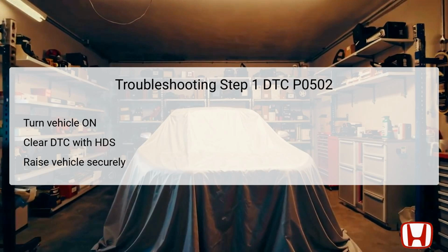At this point, entering the Vehicle Stability Assist (VSA) maintenance mode is recommended to test vehicle performance more accurately. Finally, test drive the vehicle in D position, maintaining the engine speed at 1,000 RPM or higher, while observing for any further DTCs that may appear.